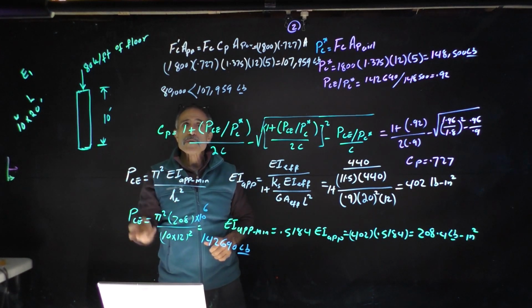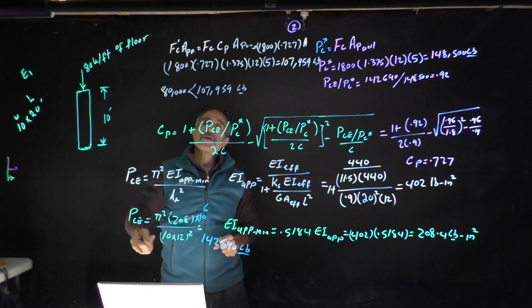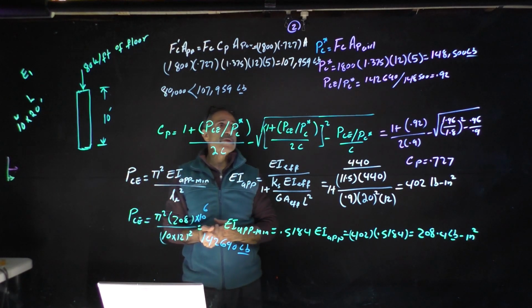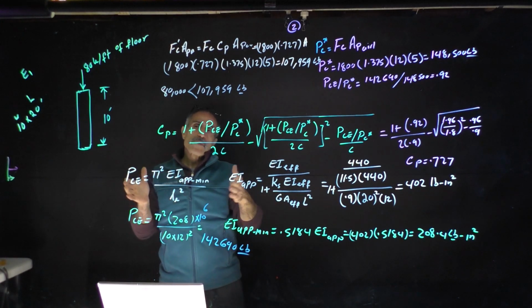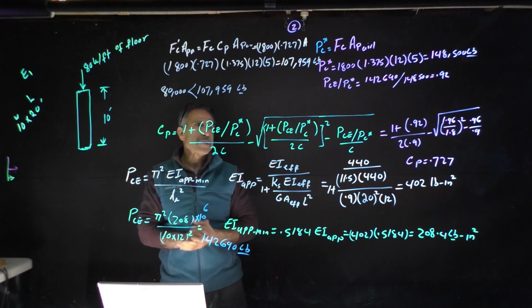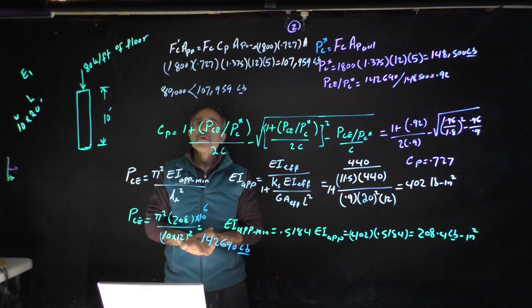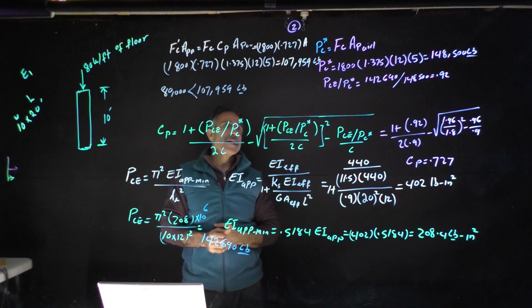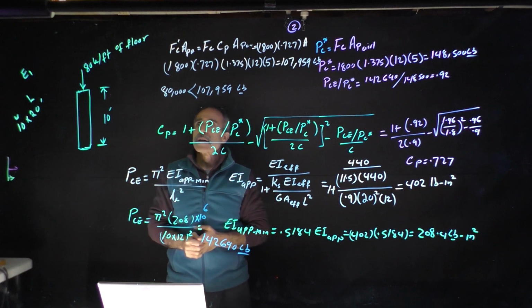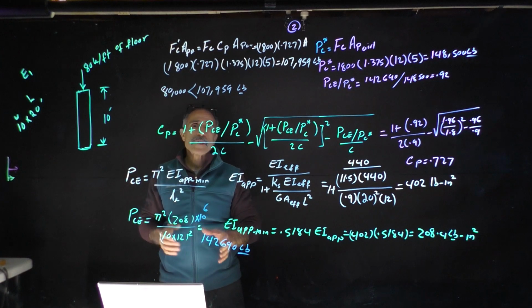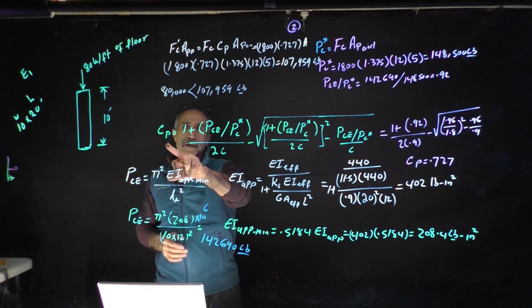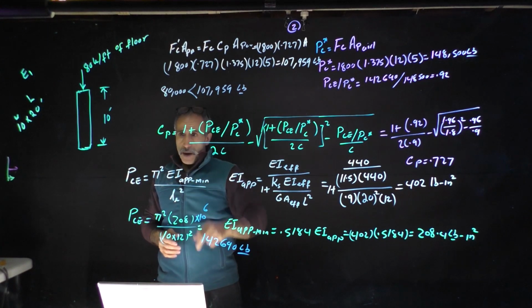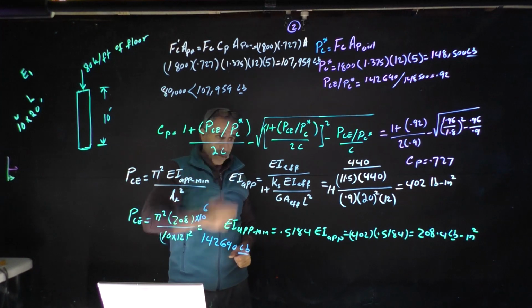You check for bending, shear, deflection, and bearing. With these things, bearing is not the issue, and they normally give you way more than enough, probably 3 to 6 inches. And for column or wall design, they're pretty strong. They can take a lot of load, like we saw here. But the most important thing is you have to find the stability factor right here. That means you have to find these equations we just went through here.